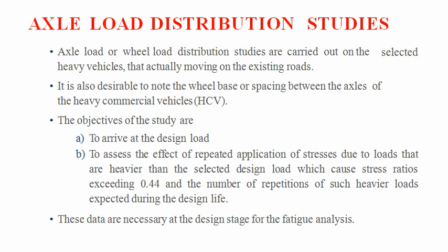Next is the axle load distribution studies. The axle load or wheel load distribution studies are carried out on selected heavy vehicles that are moving on the existing roads. It is also desirable to note the wheelbase, or the spacing between the axles, of the heavy commercial vehicles, that is the HCV.